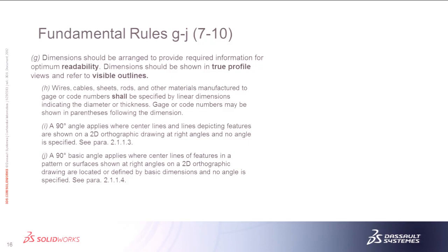Well, if it impacts the quality of your part in the end, then that actually becomes a mandatory requirement. So, little different situation, but yes. You can specify how things are done if it is impacting the quality of the function at the end. But as far as tolerance on a certain hole location or hole size, typically you're not going to need to tell them what process they need to use to manufacture it.